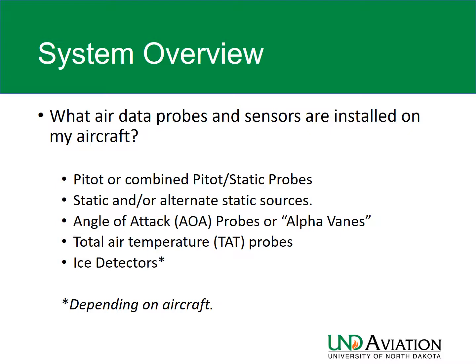So what's critical to EFIS is understanding the fact that we've got data coming from a lot of different sources. And dissimilar to small general aviation training aircraft, there are multiple pitot-static, and there's some additional probes on these aircraft, or air data probes, which are not on small GA aircraft, including angle of attack or TAT probes, as well as ice detectors. So it's important to know that depending on the aircraft, there are a lot of different combinations of these you may see.